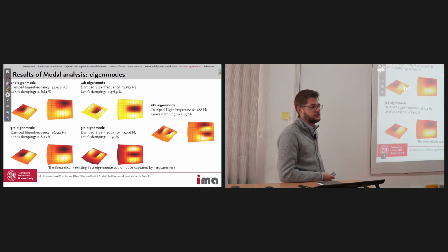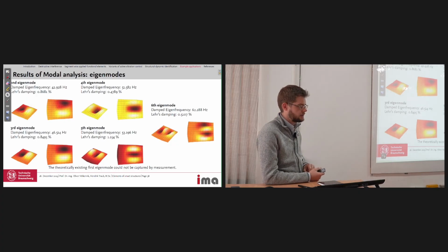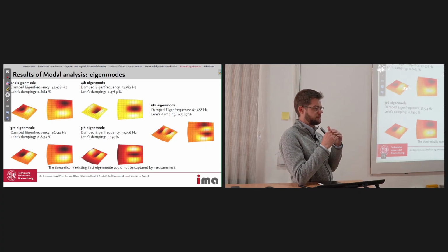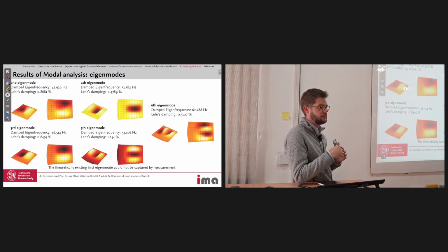It would be a structural adhesive, for example. We can calculate it, but I think the goal is to have this interface so stiff that it does not influence the transfer of the vibration from the actuator to the structure. So you would not use some kind of very elastic adhesive, but a rather stiff one that you can transfer really the vibrations without changing the behavior.